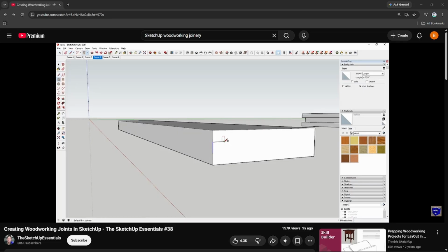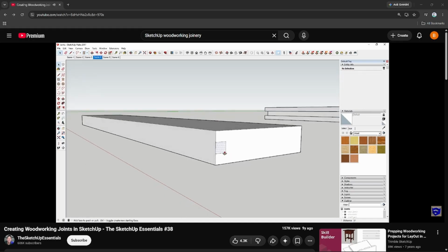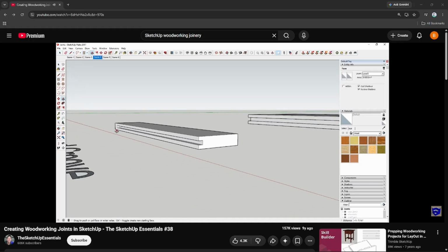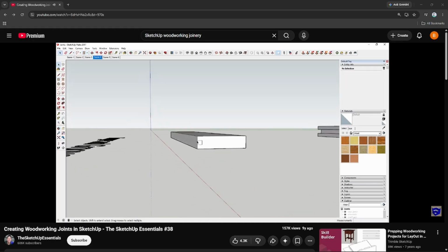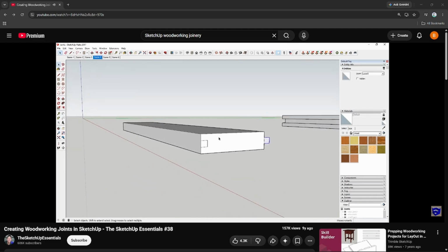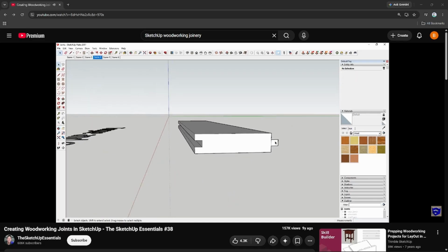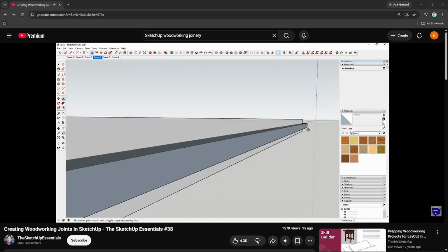Well, we could draw a 3/16 inch piece over here and then just use the push-pull tool in order to come over here and do this. But the other thing you could do before we even do that is you could also move this across your face using copy mode. And so now what you could do is you could push pull this piece to the end just like this, and then if you double click on this, it'll remember the length of the last extrusion that you did,